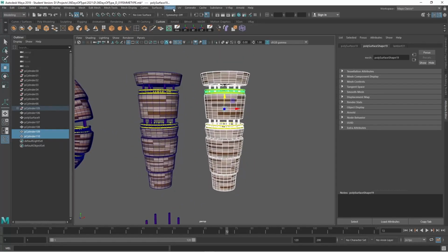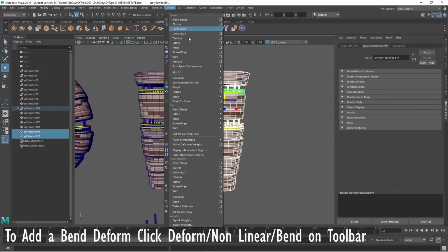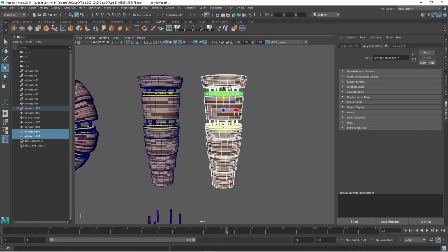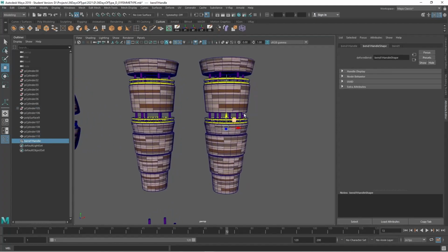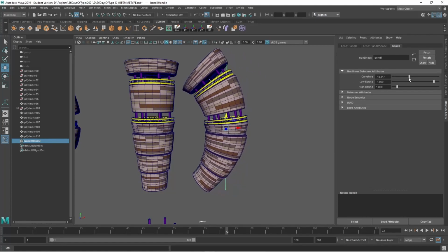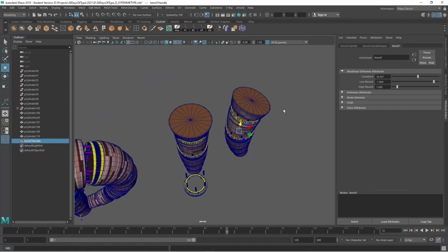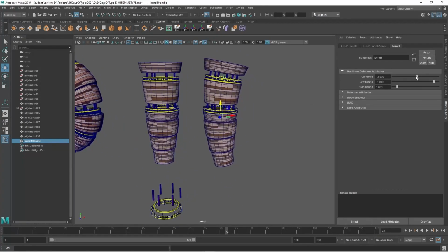When you find that, you go under modeling, then deform, nonlinear, and there's a bend option. There's a bunch of other options too, but we're going to use the bend option. I have that on my custom bar because I use it a lot. So we're going to grab that, go into the attribute editor, and go to the curvature node. Luckily, it's already bending in the direction we want. You can alter it to bend in different directions, but it just worked out for us here.